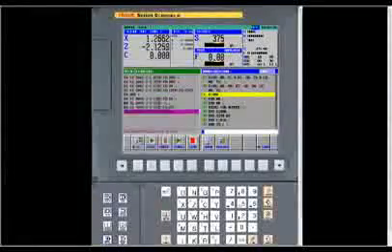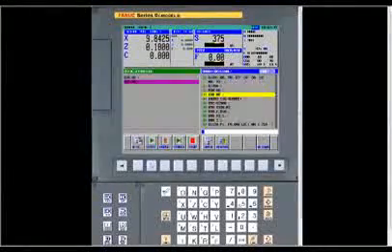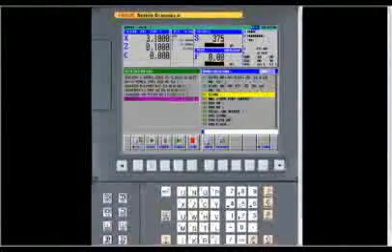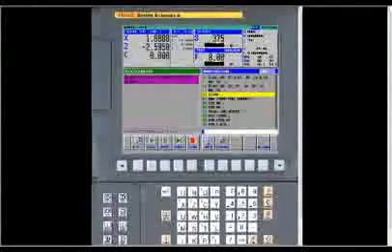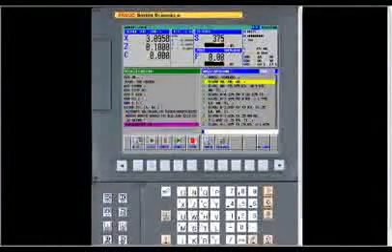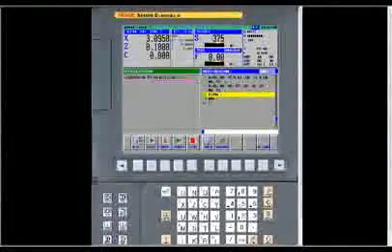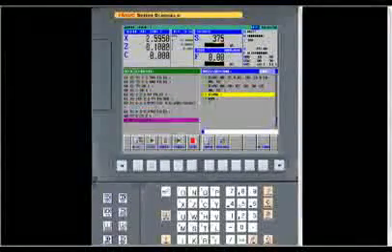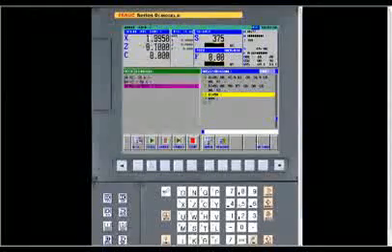But right now, it's actually creating a real G-code program on the left side, something you could take from this control or your machine that you're using, take it out of that and put it in another machine with a FANUC control that doesn't have Manual Guide on. You could use it. G-code is G-code. You could use it wherever you'd want. So it's very powerful that way.